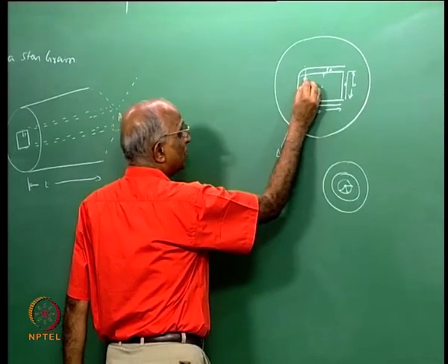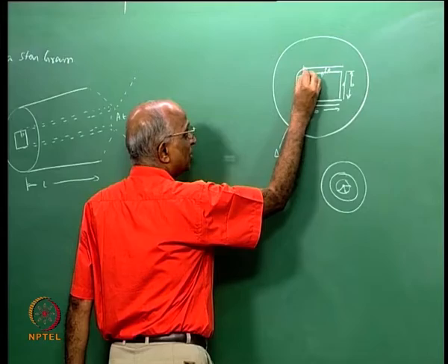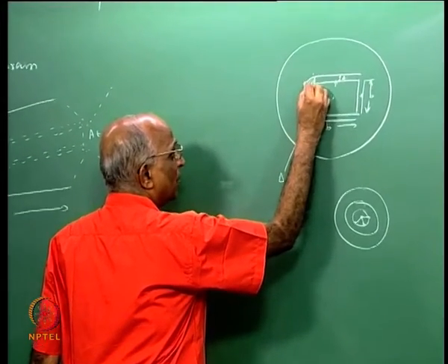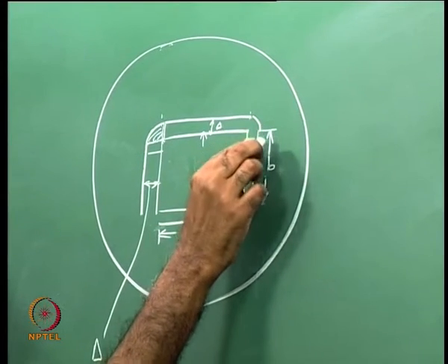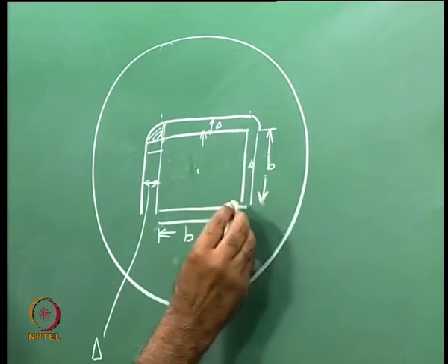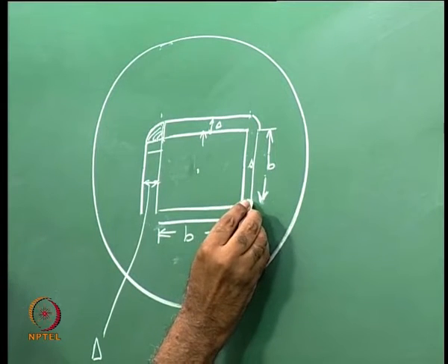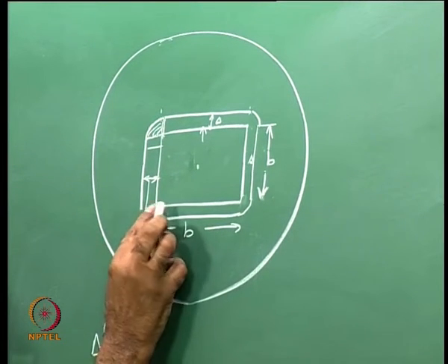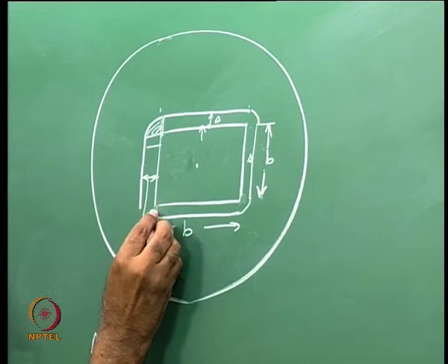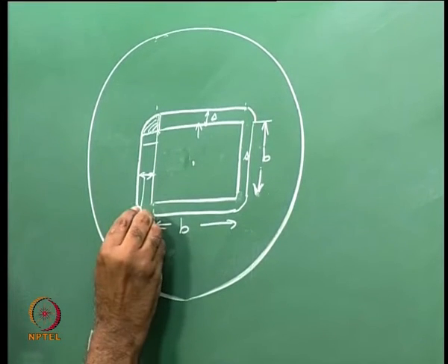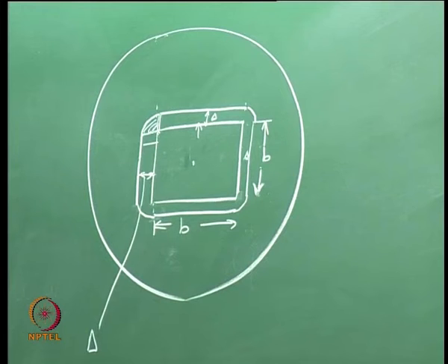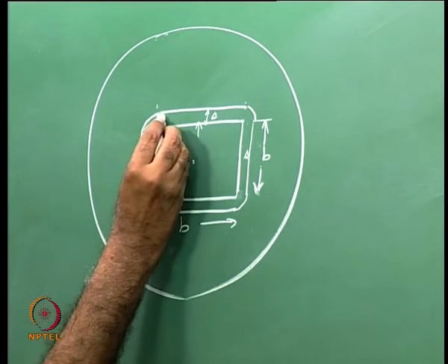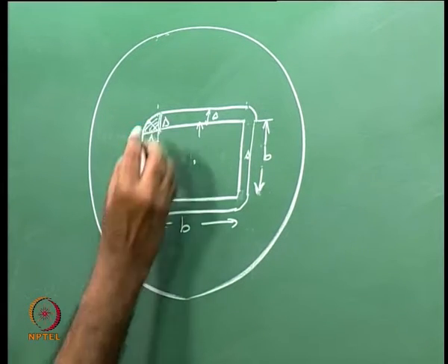But if I look at this surface, which has already evolved like this, this point will evolve like this, and therefore it will be a circle. Similarly, this point will evolve as a circle over here. That means only a quadrant, because when it meets here, it has already reached this point. When I talk of this particular point, it is a quadrant over here, and if I move over here, this is the initial surface, this is the outer surface, and it is a quadrant over here. What is the radius of this particular circle? It has evolved through a distance delta, therefore that radius is delta again.